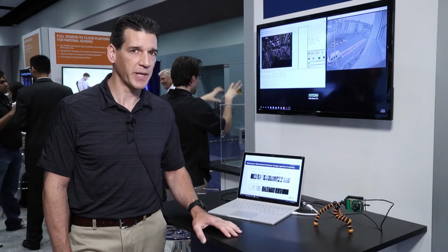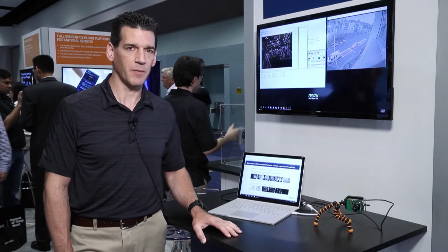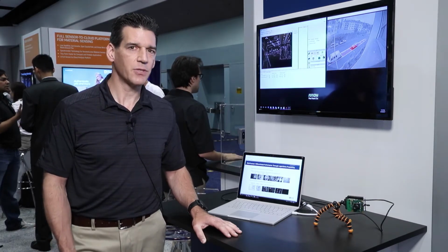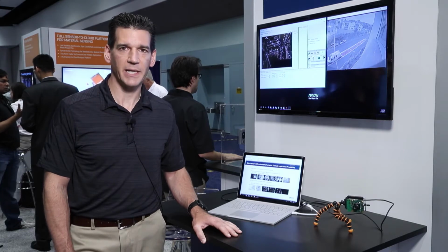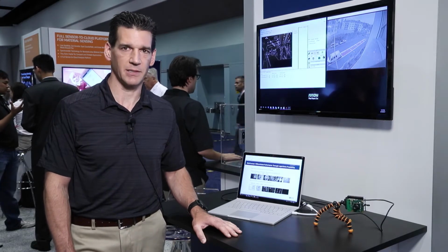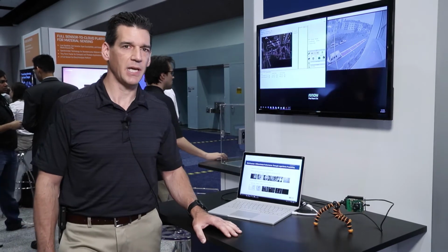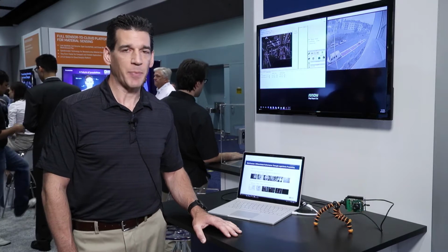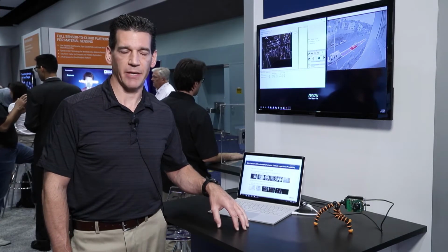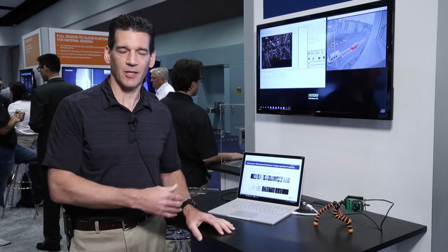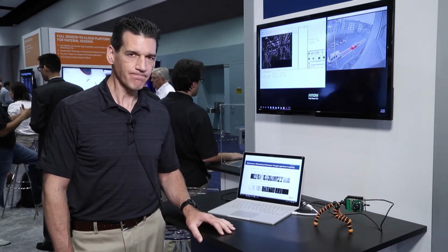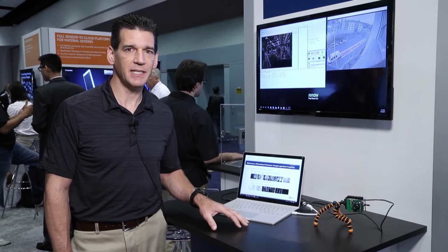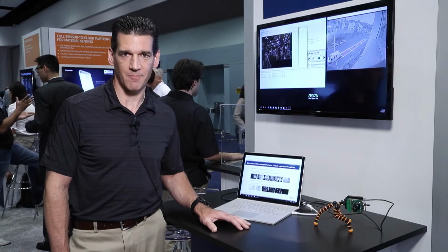Number one, it has a very large pixel size to collect a great deal of light. It also features a logarithmic sampling, and those two features combined provide for a very wide dynamic range of up to 130 dBs. Why that's important is, imagine a surface parking lot application where I'm trying to monitor cars in a parking lot. That parking lot might be very well lit in certain areas and shaded in other areas, and that illumination will change throughout the day. It's not acceptable in that application to see part of the parking lot part of the time. I need to see all of the parking lot all of the time.